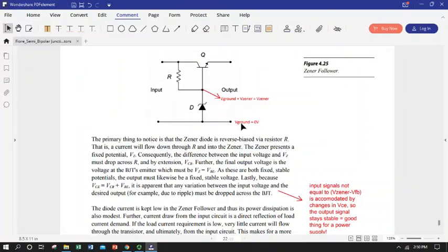So major takeaways: the transistor will only conduct current between the collector and the emitter if we have overcome the forward bias voltage at our base emitter junction, and when we do that, we are by definition flowing a little bit of current into the base. Our collector current, if it is not constrained by other things in the circuit, will be related to the base current by our beta.